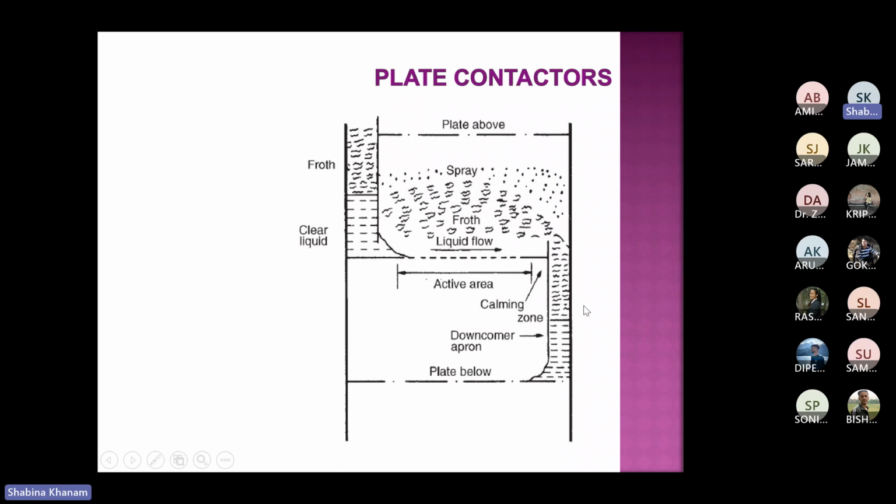In that way there is a tendency that hold up or liquid filling will start in the plates above. And that we call the flooding condition. It means the vapor velocity should not be so high that flooding will occur. Otherwise, liquid is everywhere, and the interaction between vapor and liquid is not possible. So the velocity should not be too high, to avoid flooding. That is one point.